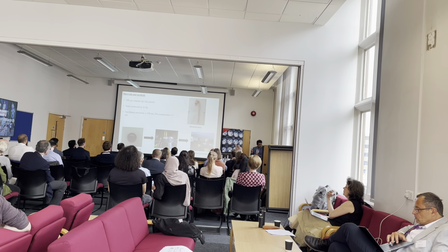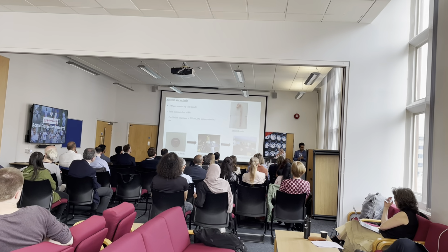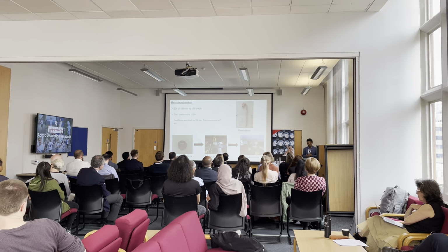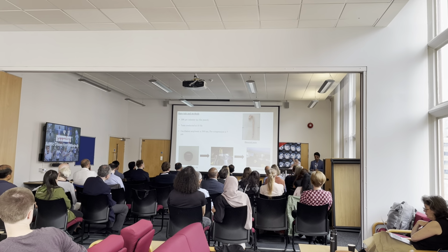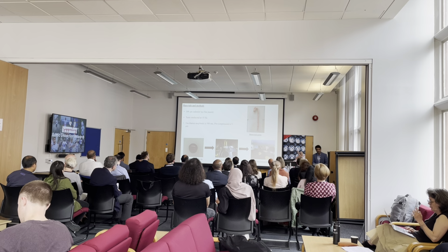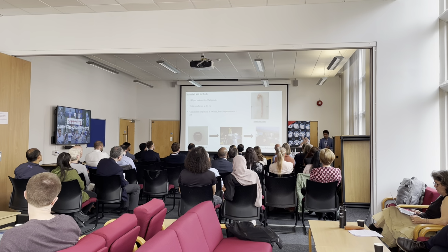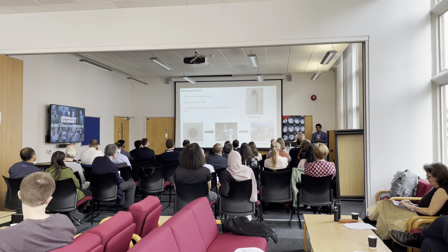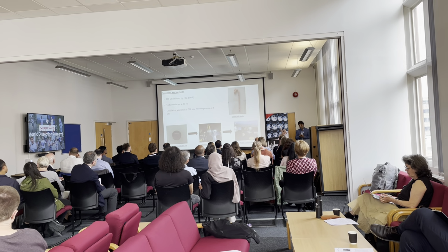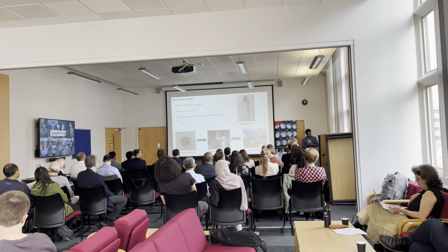So this was the materials and methods, in which we had the dissected aorta, which you can see here. We utilized a 100 micron indenter tip. There were two reasons for this. One is that we wanted to test at the micron length scale. The other was that we tried to use a flat punch because, compared to other punches, of creep. In viscoelastic tissues, we also have the property of creep, where the strain and the interaction between the tissue and the tip of the indenter change with time. To avoid that and to make sure we had a constant surface area across these indentations, we used a flat punch tip.